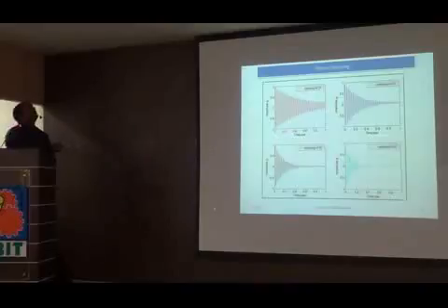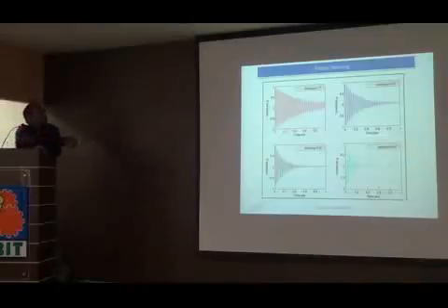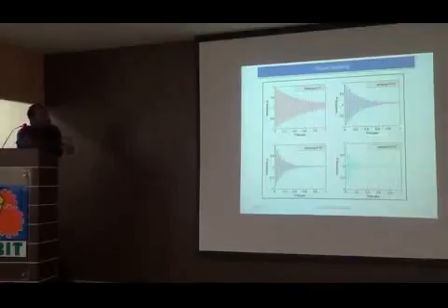And if you see the E by rho ratio, which determines the natural frequency of the structures being designed, E by rho for magnesium, aluminium, and steel are almost the same. So that means if you design a fixture with either aluminium, magnesium, or steel, your natural frequencies are going to be the same. But damping is going to be better with magnesium, so we prefer magnesium alloys for fixtures.